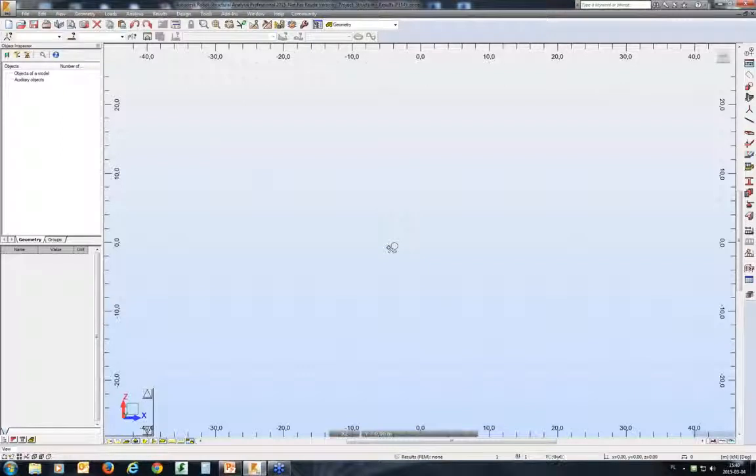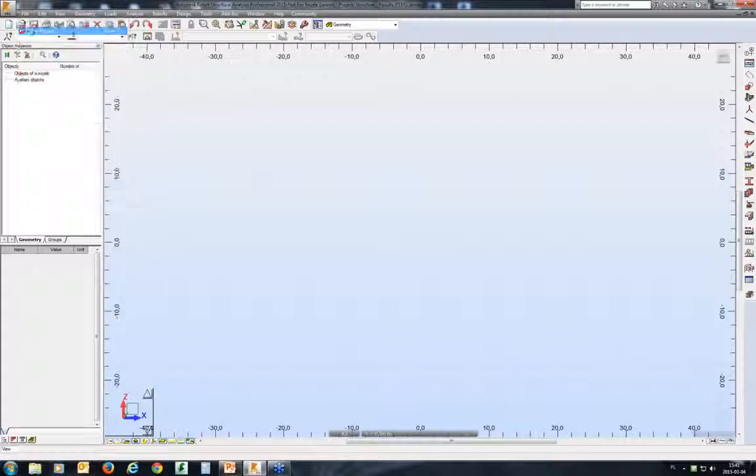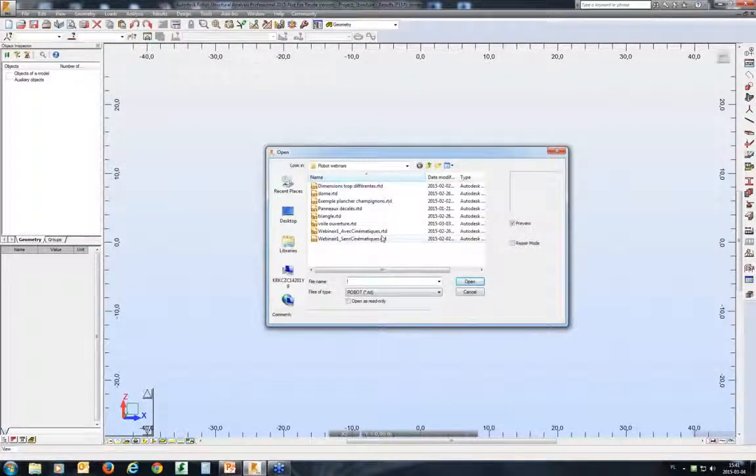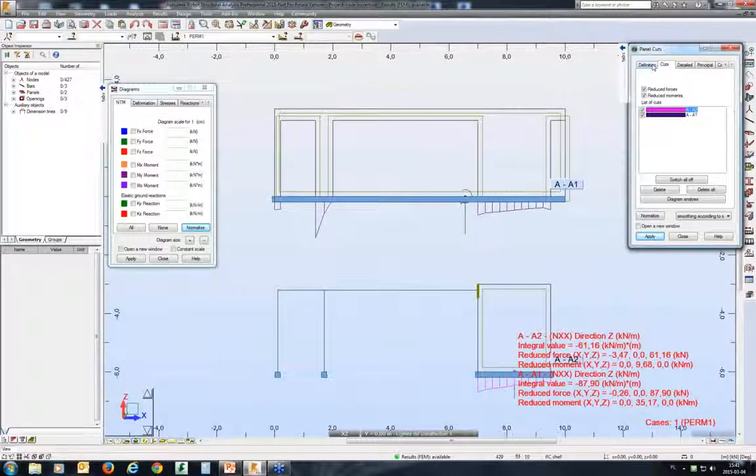Okay. All right. Regarding cuts, is there a way to export or import coordinates for the cuts, just like when modifying panel contours? Export, no, like an Excel file doesn't work. If the question is how to modify that, I can show. If I open my model, okay, so I defined the cuts to be at the bottom edge of the walls, but you may select one of them, for example the bottom one, and you may change the coordinate.